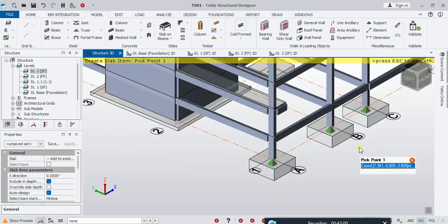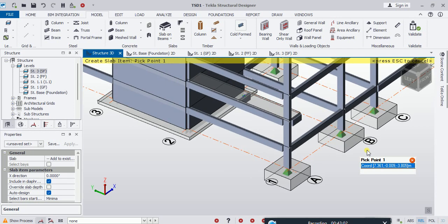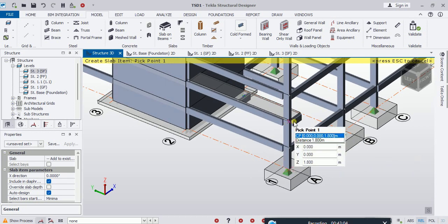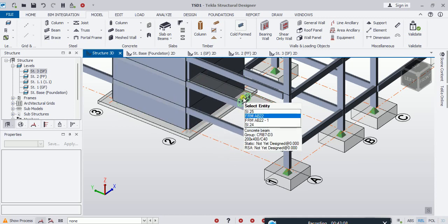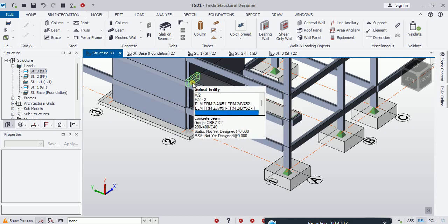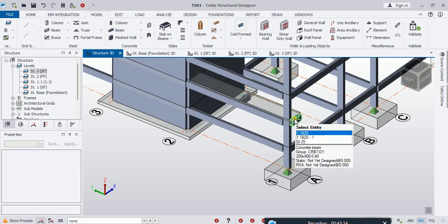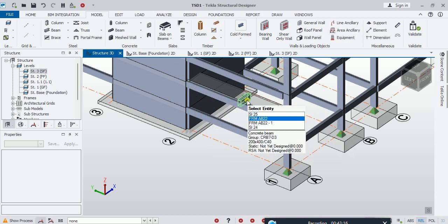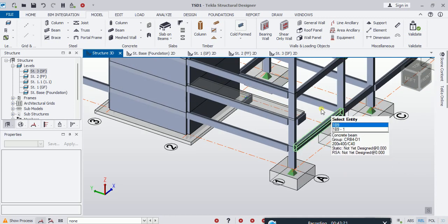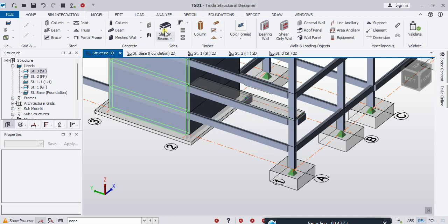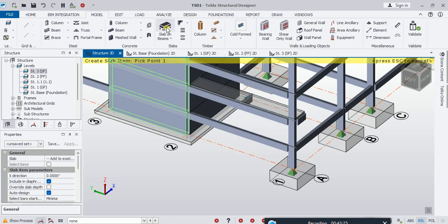Have you seen what I have done? I have done the landing, right? Now this is a function of having this beam and this beam. Why do I have this beam? For drawing the slab, I use this beam and this beam, right? For this beam, to draw the stair, because it should go to half, right? So what I'm going to do, I'm going to go to slab.